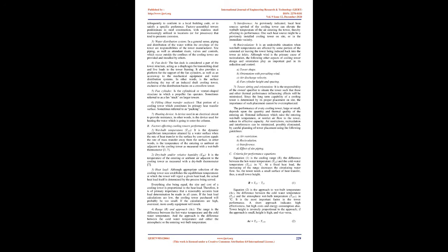2. Cooling towers basics. A. Structural components. Cooling tower structure must accommodate long-duration dead loads imposed by the weight of the tower components, circulating water, snow and ice, etc. It must maintain its integrity throughout a variety of external atmospheric conditions, and despite a constant internal rainstorm. Wide-ranging temperatures must be accepted, as well as the corrosive effects of high humidity and constant oxygenation.